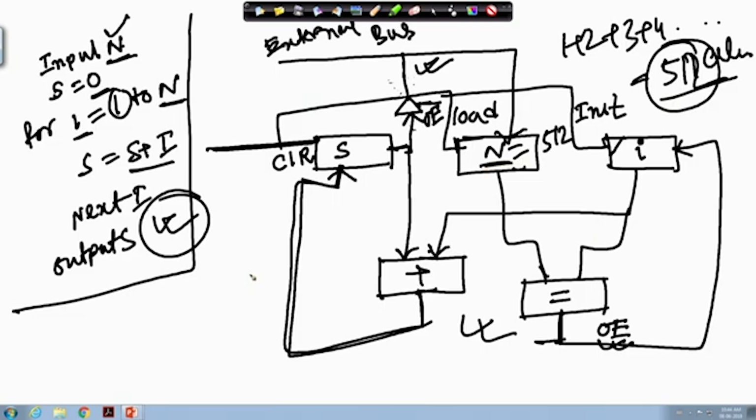So, if you see area wise, what is the benefit of this circuit? Area wise, I require only 3 registers, 1 adder and 1 comparator. For 512 I need 511 adders for case 1, and for case 2 it is fixed, 1 multiplier and 1 incrementer, but here I require only 1 adder and 1 comparator, and registers are required there also.